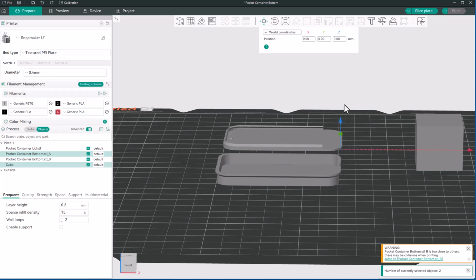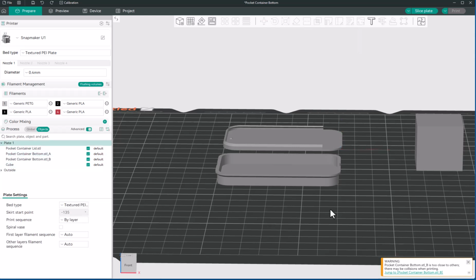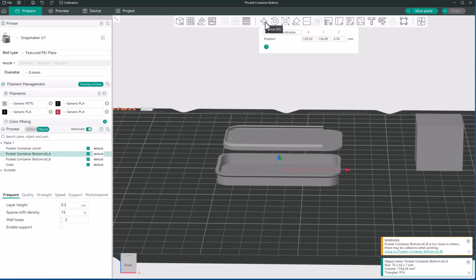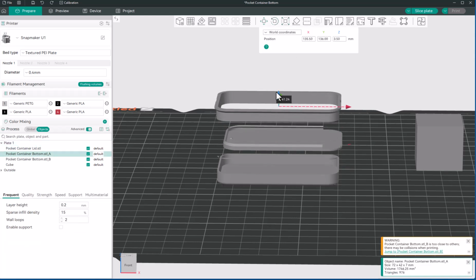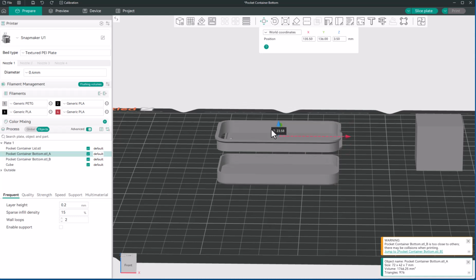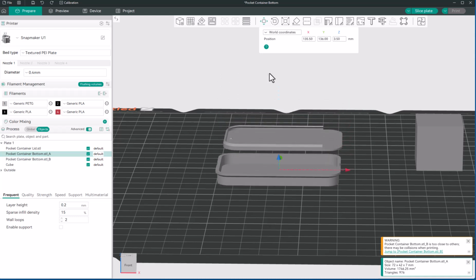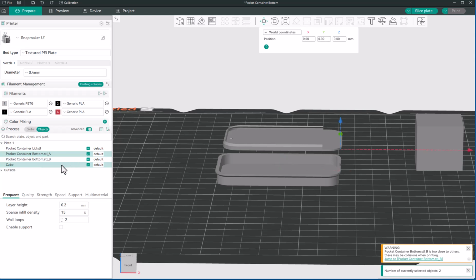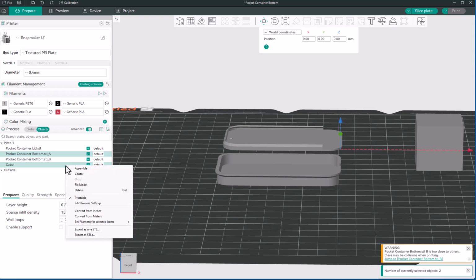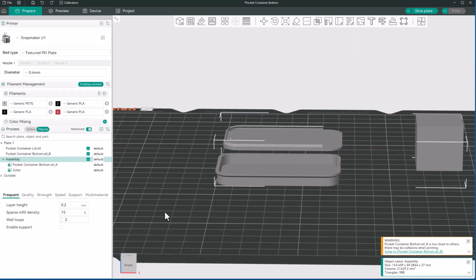Nothing moved. Okay. And the reason it didn't move is because we never hooked this and that cube together. Here's my top of the bottom, and my cube. We never hooked it together, so when I let go of this, it goes down. Okay, so we're gonna hold Control in, select A and the cube. Got them both selected. Then I'm gonna right click and hit Assemble.